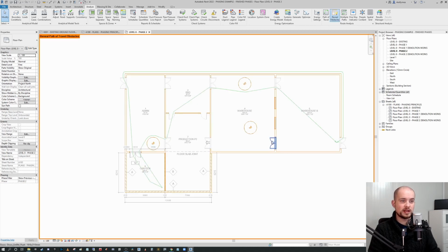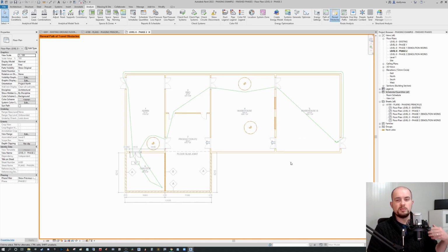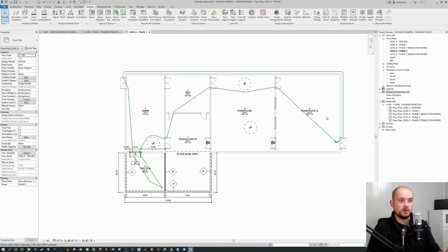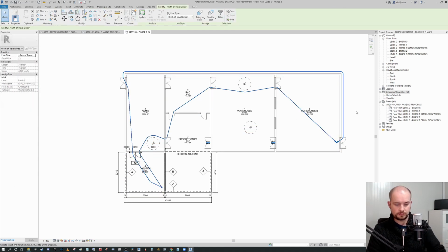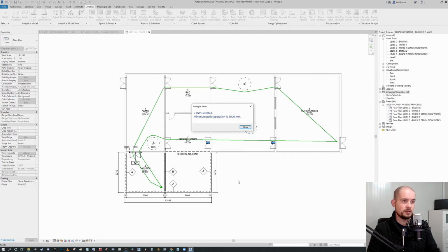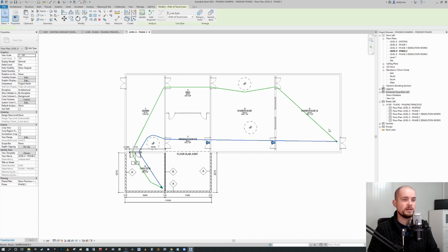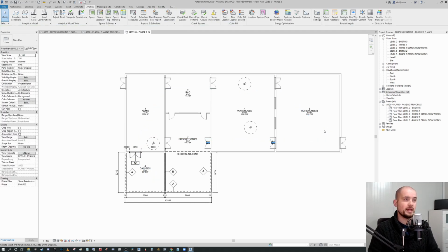Now these one-direction indicators, they don't show as obstacles, but they merely show that the door only functions in one way. If I was to delete those 2 and change the orientation, the direction that the path is going from here to here, you will see that it won't recognize those doors as a problem. It'll go straight through because it's in the direction that the doors are set as the flow direction. Okay, so closing that again.